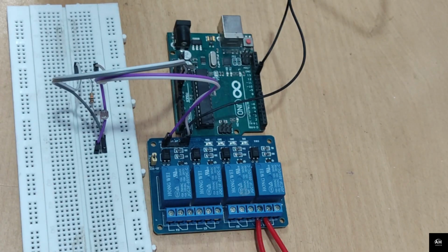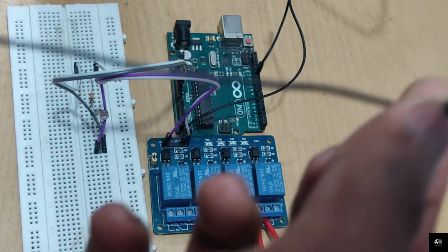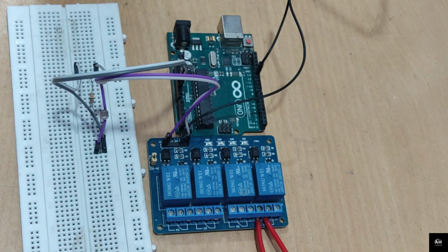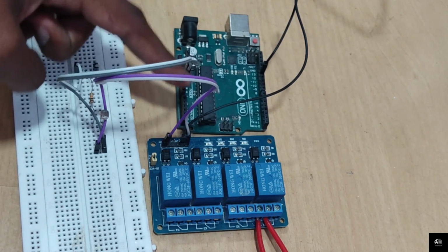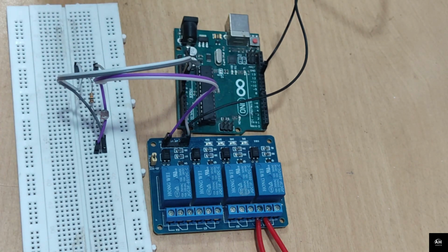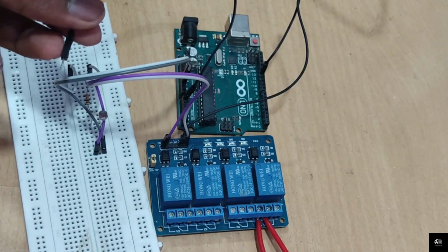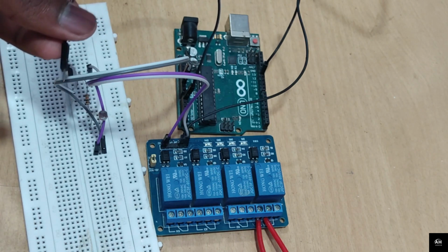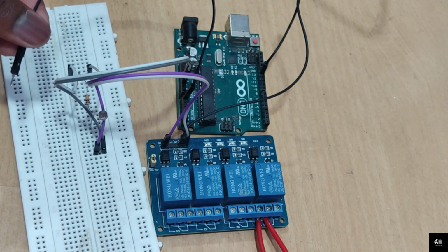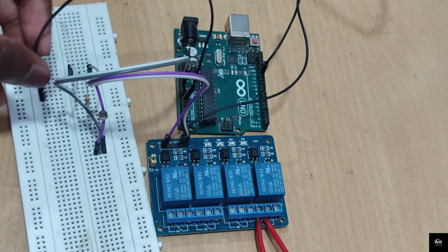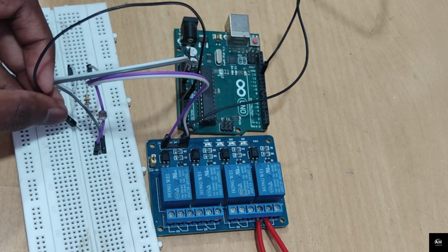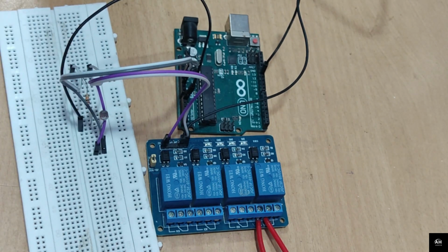Once we have connected the ground and the 5 volt with our Arduino board, we will connect this black jumper wire to A0 on the Arduino board, which is here. You can see this is the A0 port using which we can get the analog input. So we will connect it there, and the other end of this black jumper wire will go into the intersection of the resistor and the LDR, where we have connected it in a common input. So we'll connect it there, and our sensor will be able to send the analog signal to our Arduino board.